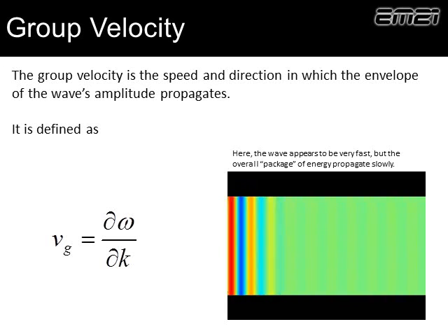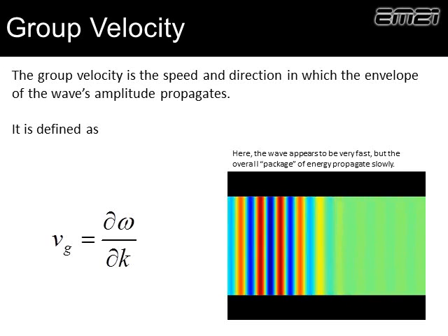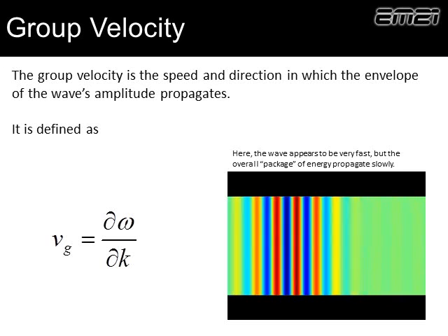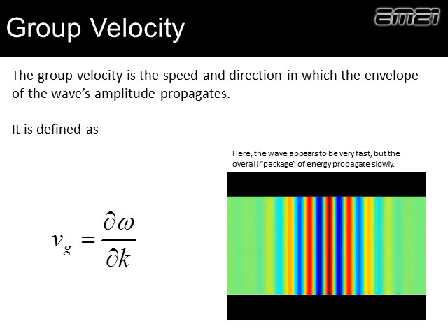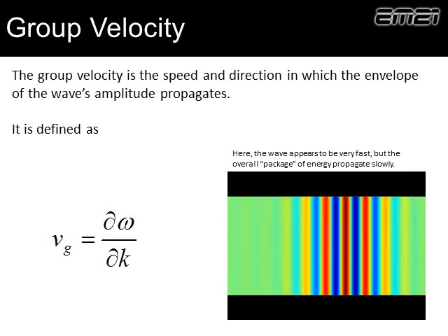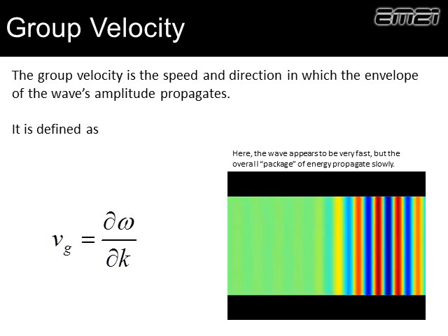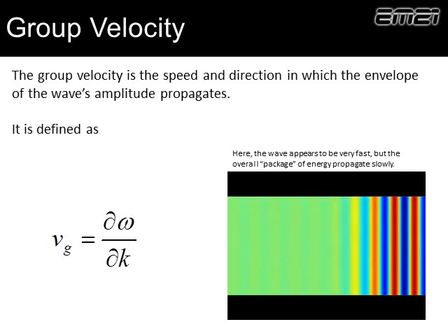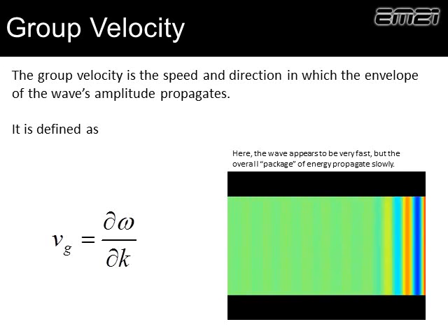The next topic is group velocity. And when we talk about group velocity, we're talking about something that's no longer a pure sine wave. We're talking about a spectrum of frequencies. And there's certainly the potential here that each frequency can travel at a slightly different speed. And if we get this bandwidth due to some group of frequencies, if you will, or a signal, that could potentially travel at a different speed than any one of those pure sine waves by themselves. So we're really looking at sort of an envelope effect. How fast does the envelope travel?